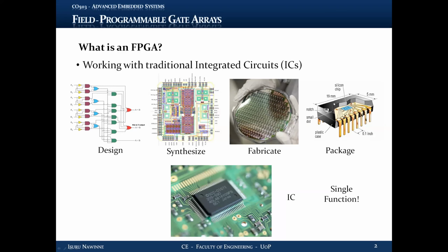And then when you have the chip made, you put that chip into a package. The packaging provides insulation from electromagnetic activity and all sorts of interference, as well as a means to put the chip into an overall circuit, into a circuit board, right? You have different types of packaging. The one in the picture is called dual in-line, where the pins are in two lines, and there are all sorts of other packaging, surface mounts, and so on.